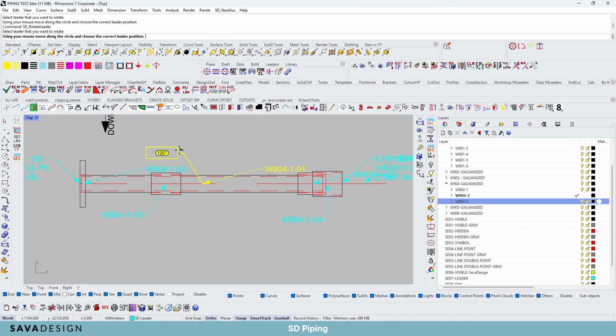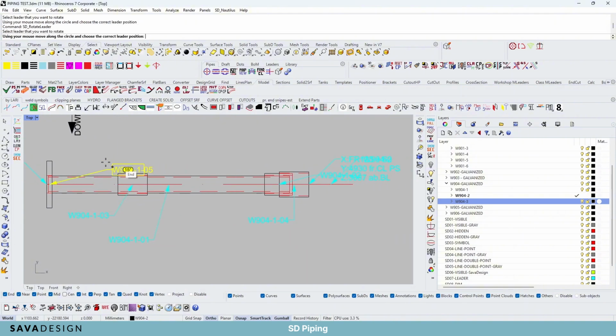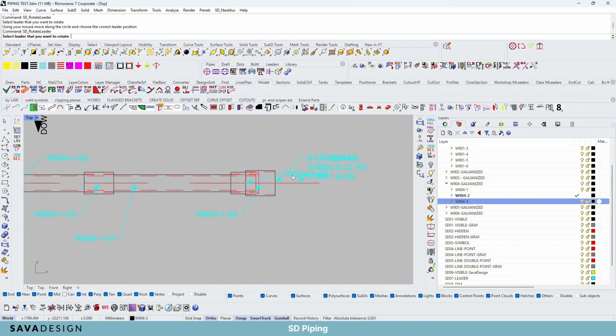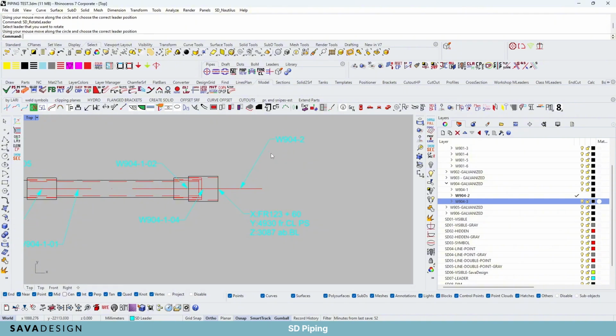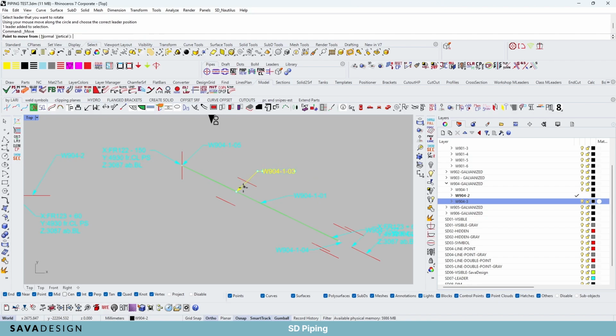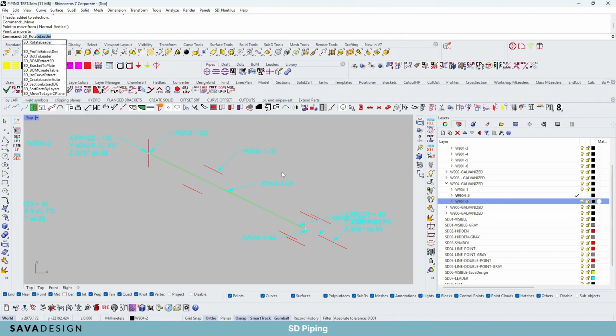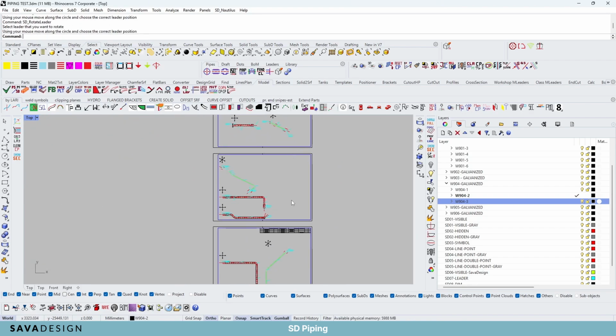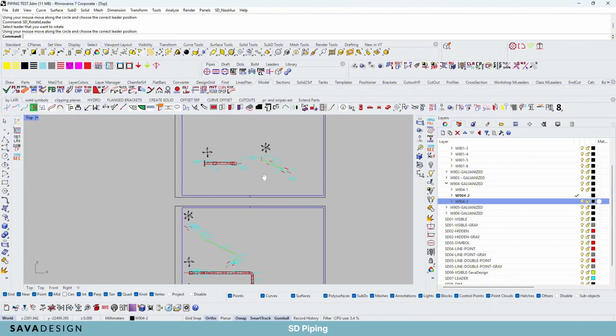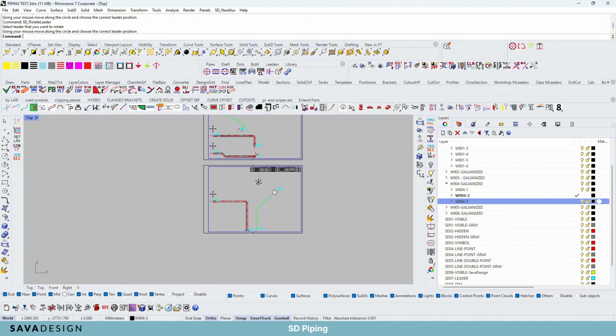So you see you have a preview basically where the leader will be positioned. So you select the position you want, and it moves the leader there. It basically comes down to right click, left click, and just playing around and moving things around to better fit your needs. Besides the orthogonal projection, we have the isometric projection. This is the perspective view of the spools I was talking about. Here we can go through quickly, set up the leaders how we want them to be. And we can repeat this process and basically play with the technical papers generated how we want.